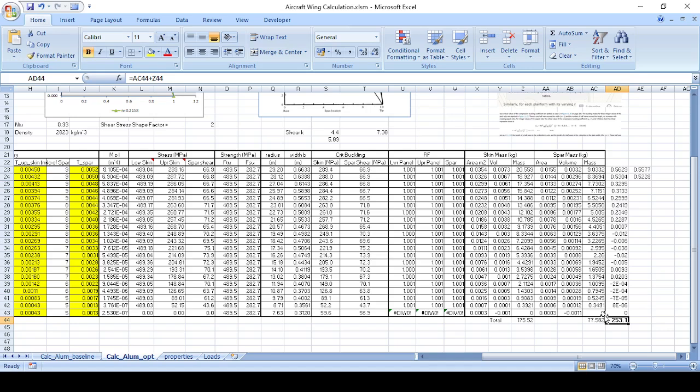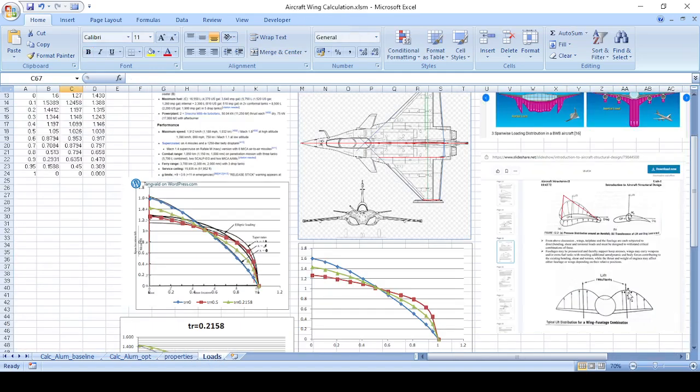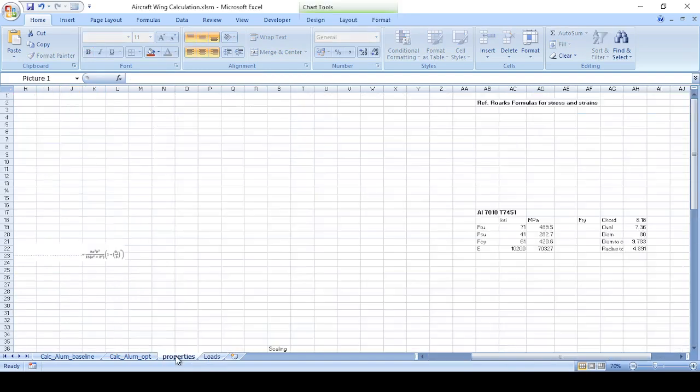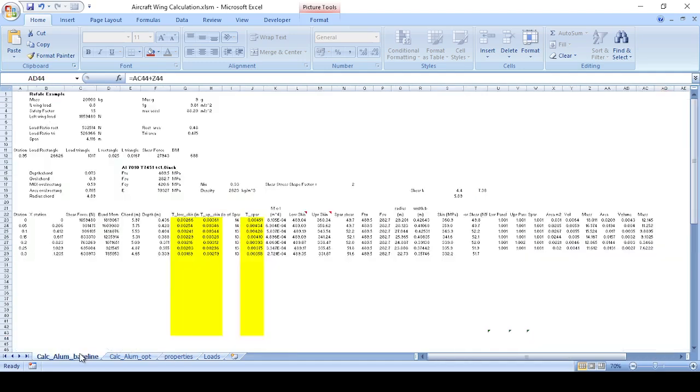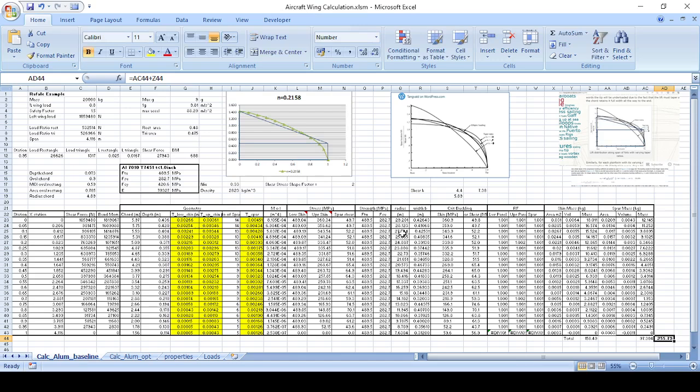And again, I didn't use a civil aircraft because that would be even more complicated, because that only has 2 spars, but then you will have stiffness along the skin. Instead of having this multi-spar design, you will have just one stiff spar at the front, one stiff spar at the back, but then you have stringers going down the middle, and those stringers are effectively breaking the panels again, but your shear is there, and you then have to analyze those stringers separately to make sure that they don't buckle themselves and they provide enough support to the skin. So it's a little bit more complicated, but you can also put that in a spreadsheet, and it just makes the spreadsheet a lot bigger.